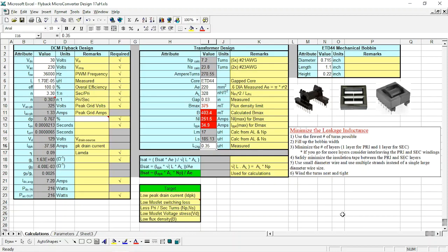I didn't spend any money on this project. I used everything that I had laying around. I had certain wire laying around, magnet wire, in a few different sizes. Based on my core size and the lengths and everything, I was like, what can I fit? I knew I could do around 7 turns and maybe 24 turns. So that's what I adjusted these numbers to give me basically this.